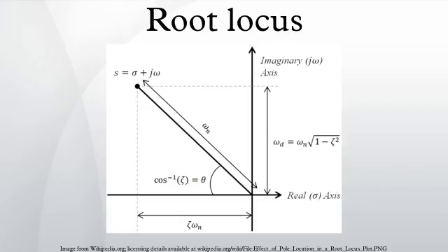In control theory and stability theory, root locus analysis is a graphical method for examining how the roots of a system change with variation of a certain system parameter, commonly a gain within a feedback system. This is a technique used as a stability criterion in the field of control systems developed by Walter R. Evans, which can determine stability of the system. The root locus plots the poles of the closed-loop transfer function in the complex S-plane as a function of a gain parameter.